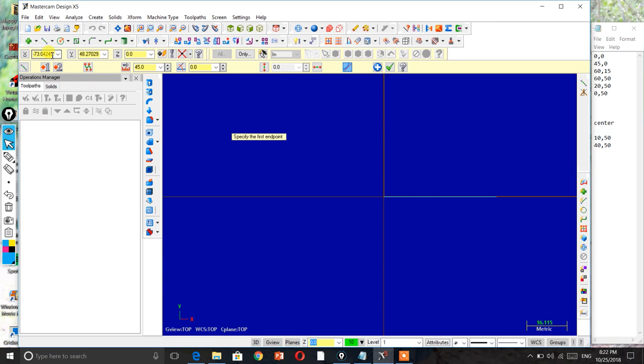Next, you can click over here, or you can also choose the same point 45 0 again, and then 60. I am selecting this way, selecting the end point, and then we have to write the second end point. The second end point for this line is 60 and 15, so 60 comma 15. And third is again a line starting from this point.